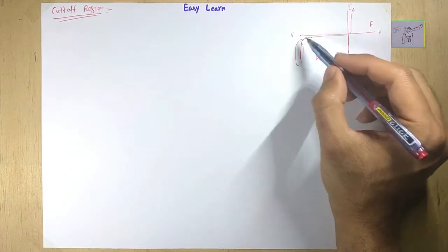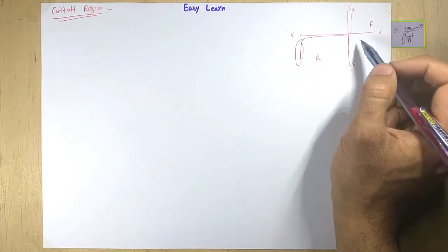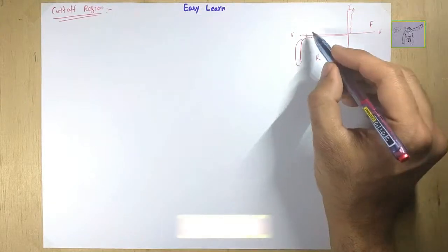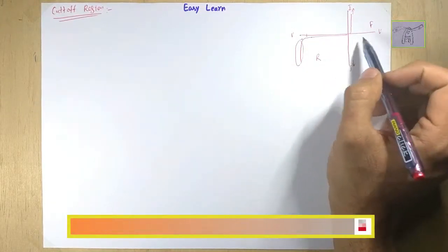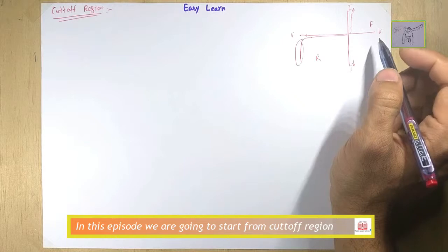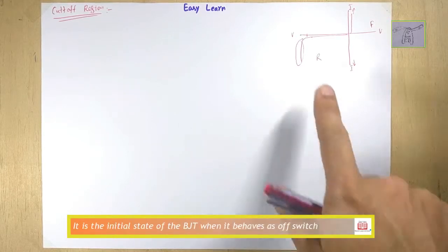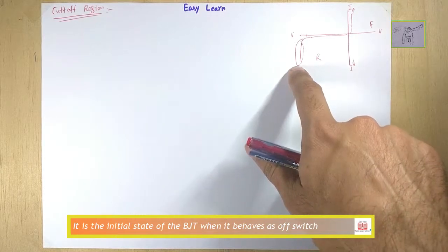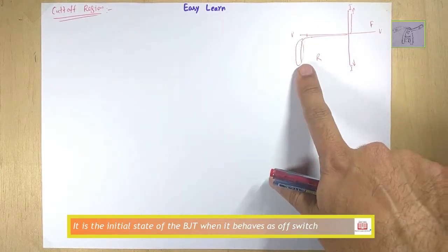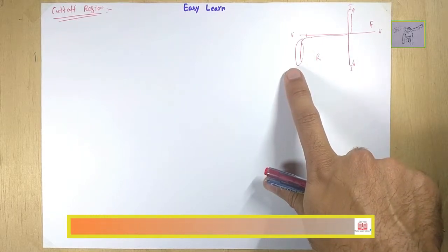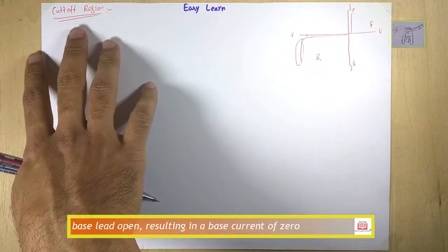But this is the breakdown region, which is reached when we cross a certain voltage limit. The manufacturer does not design a diode to operate in this region. If we cross this threshold voltage, the diode will burn, and the current increases suddenly. The same is the case for the cutoff region.